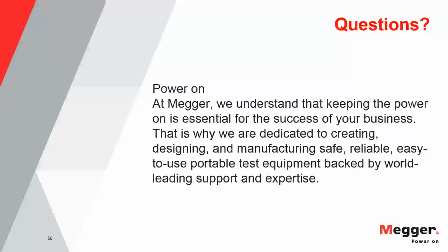Now, what Jason also explained very nicely was that in IEEE 400, you have this combination test called a monitored withstand. To make this clear, this is a fully standard compliant VLF test, as you have to do it anyhow, but you use the partial discharge as a trend indicator.